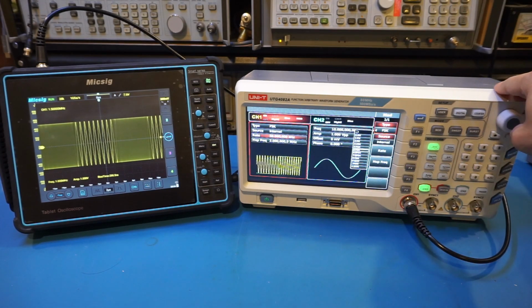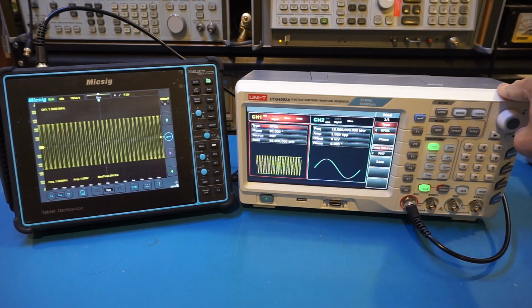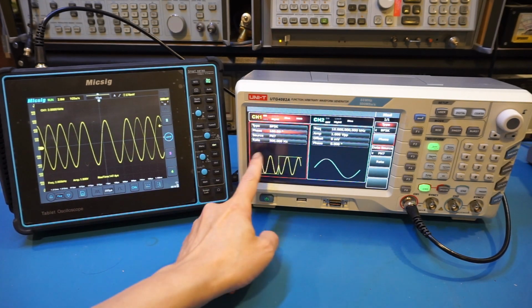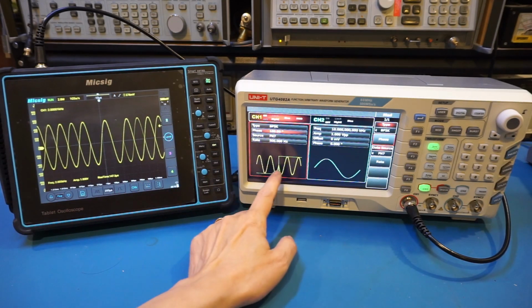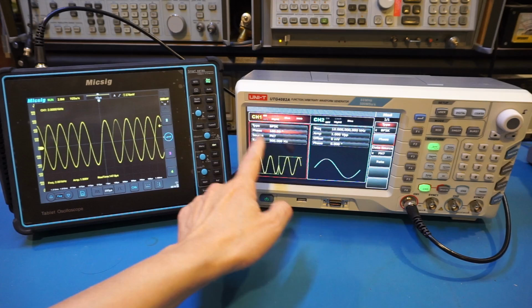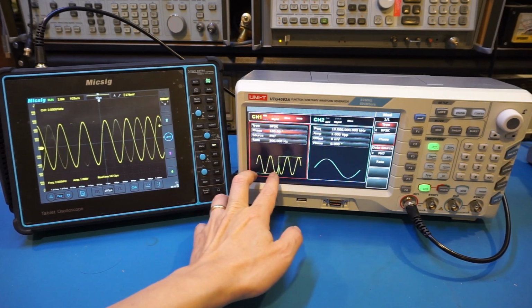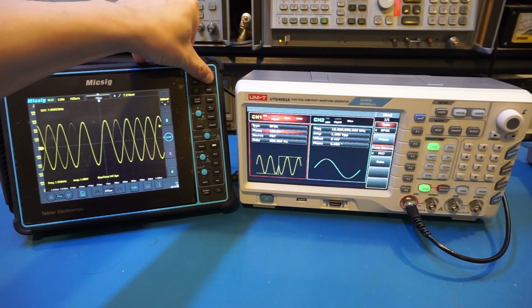Now, of course, we have a lot of other options we can test. The phase shift keying, that's probably very similar. Let's do the BPSK. Now let's briefly take a look at the binary phase shift keying here, and that essentially is using two different phase signals to modulate the carrier frequency. So you can see here, right now we're changing the phase to be 180 degrees, so these two signals essentially have the opposite phase. Let's briefly pause the capture here.